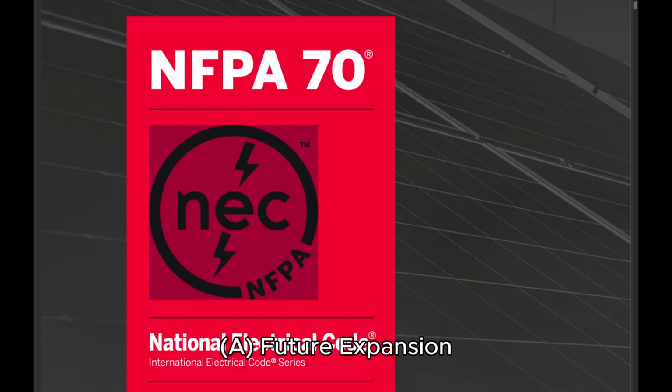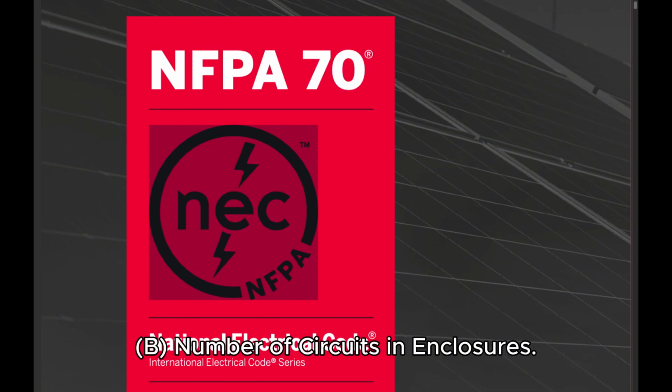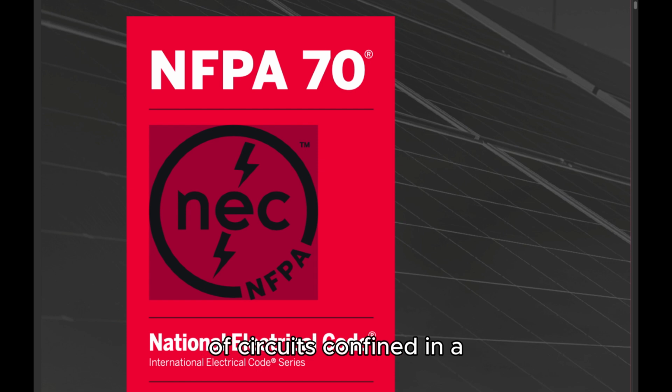90.8 Wiring Planning. Future expansion and convenience. Plans and specifications that provide ample space in raceways, spare raceways, and additional spaces allow for future increases in electric power and communication circuits. Distribution centers located in readily accessible locations provide convenience and safety of operation. The number of circuits in enclosures. It is elsewhere provided in this code that the number of circuits confined in a single enclosure be varyingly restricted. Limiting the number of circuits in a single enclosure minimizes the effects from a short circuit or ground fault.